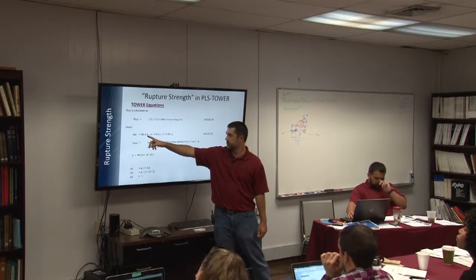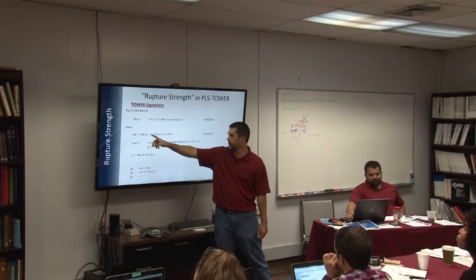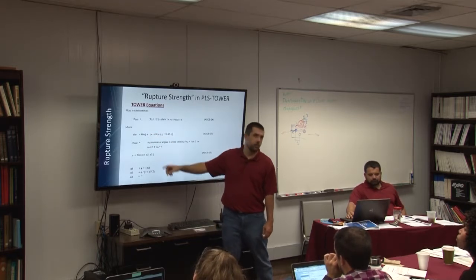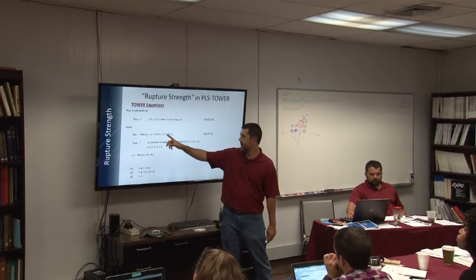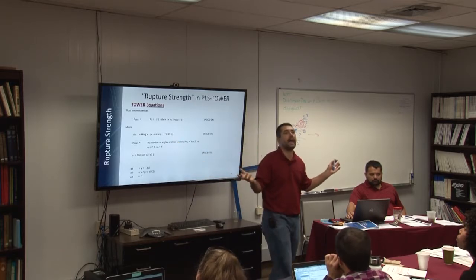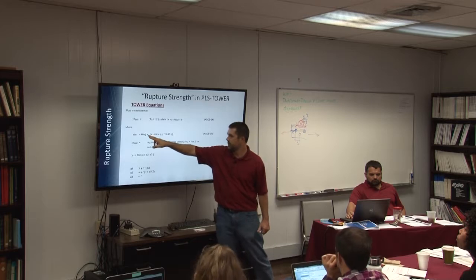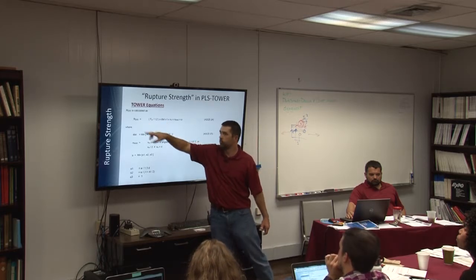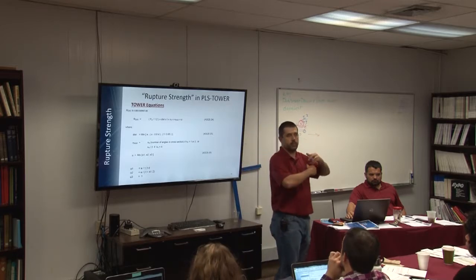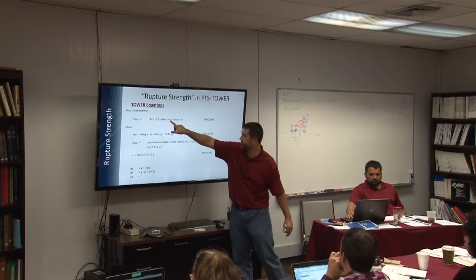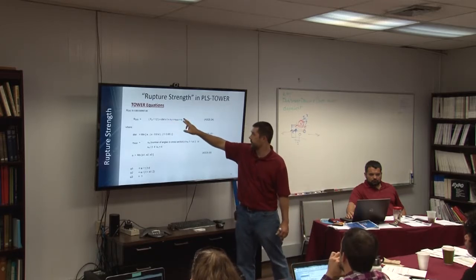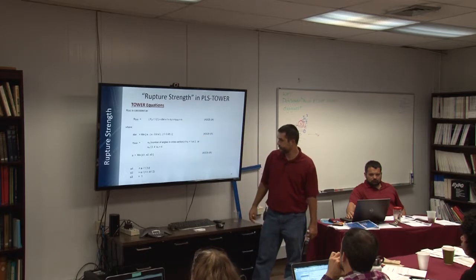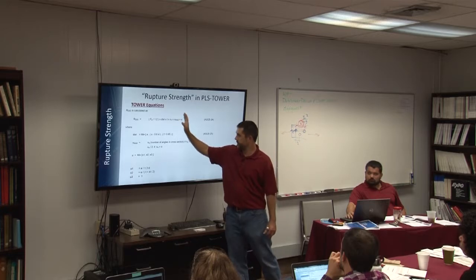So if my end distance is 1 inch, my spacing minus 0.6 of the bolt diameter is 2 inches, and my edge distance divided by 0.85 is 1.5, then it takes my end distance of 1 inch and feeds it into this equation. And this is the rupture strength per bolt, and then they multiply by the number of bolts, the number of bearing areas, and a strength factor. Okay? So that satisfies almost everything.